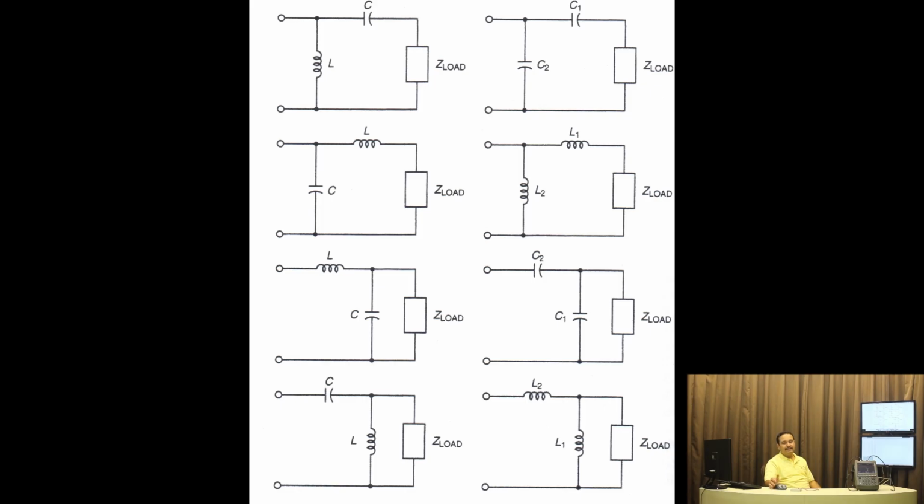Usually it has to be a combination of L and C. Avoid a resistor because a resistor is going to add noise before your transistor, and this is definitely what you don't want to do to have the lowest noise. So some sort of L and C combination is a possible solution. Of course, for a distributed case, you could implement an inductor with a narrow transmission line, a capacitor with an open stub, and so on.